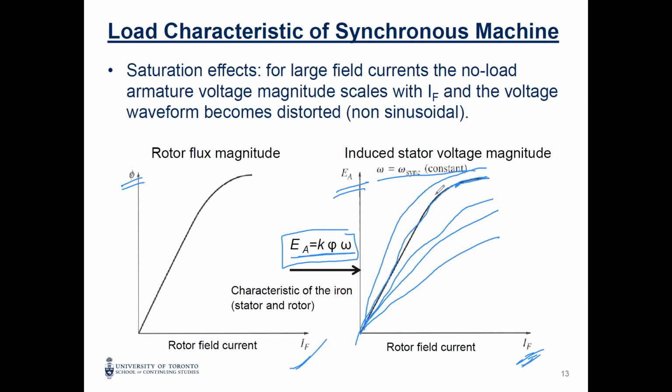Usually, the machines operate very close to the knee point. Not after, because of saturation, and not before. Almost at the edge.